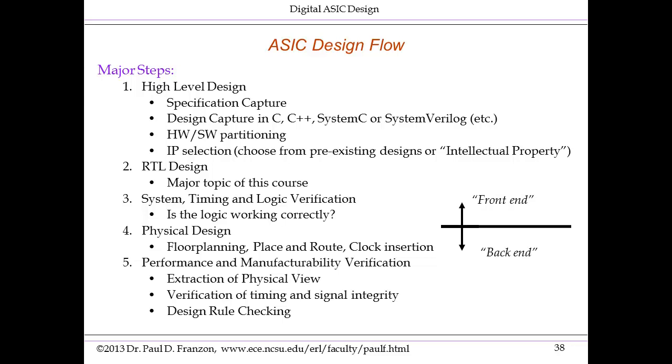The next step is the next level down design, RTL design, the register transfer level. Though it would be lovely to be able to go straight to logic from the high-level description captured in C or SystemC, in practice, though it is possible, the logic that's produced is very inefficient.